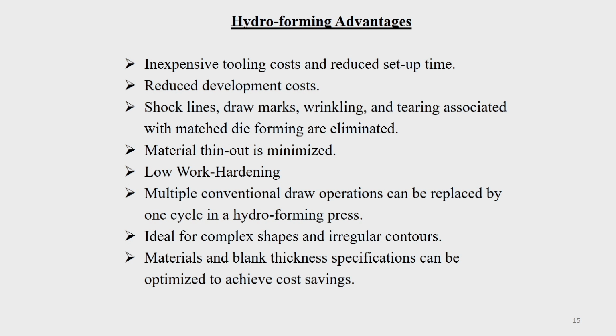The advantages of hydroforming are inexpensive tooling cost and reduced setup time. This is one biggest advantage. Once you fix it, then you can start making in large number. So, that is the inexpensive tooling cost, but machine cost is high. It is not very high also, but the tooling costs are not high. It is very cheap, and not only that, the setup time is also very much reduced. It is a very simple thing only to fix it. There is nothing like exactly arranging these parts and matching them. So, that is not coming into picture.